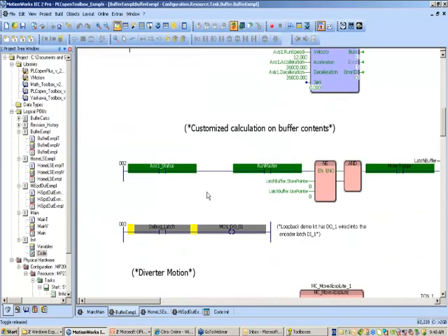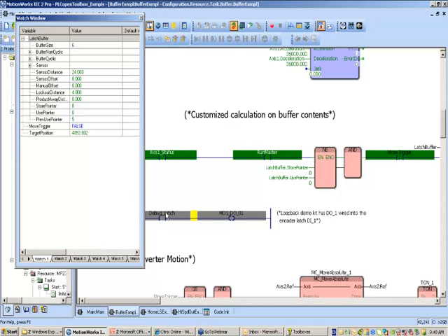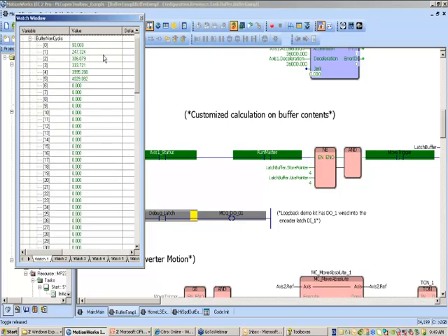I can run the master, and now I'll capture some inputs. I'm working with a special demo kit that we have where we have some signals looped back. So some of the outputs and the position of our main axis 1 is fed back into the external encoder. So if I trigger some latches to happen, we see that my storage pointer just incremented. Here it is again. And if I look at the buffer, you can see that every time I get a latch, it'll store it into the next location. And when it reaches the top, it'll wrap around.